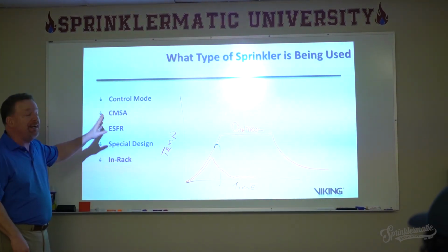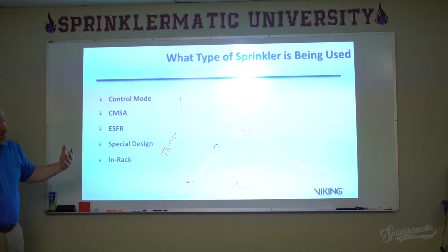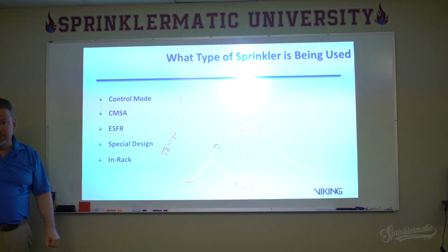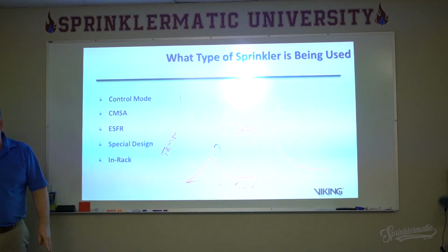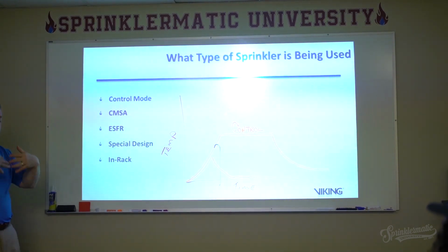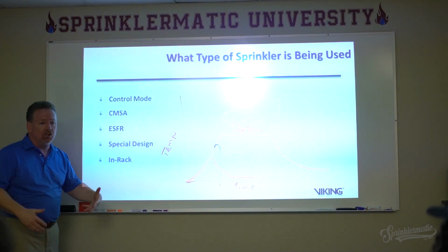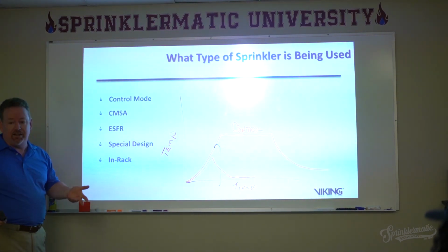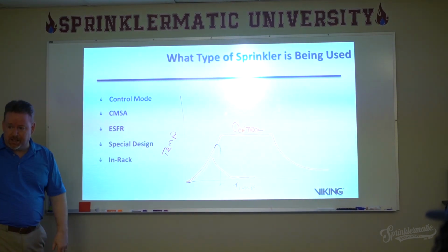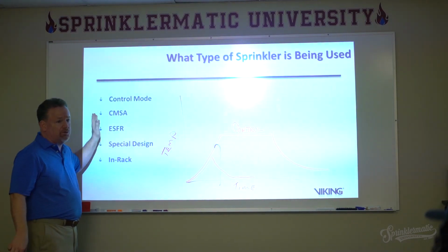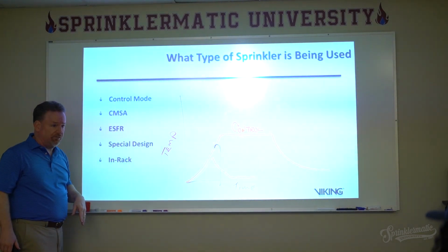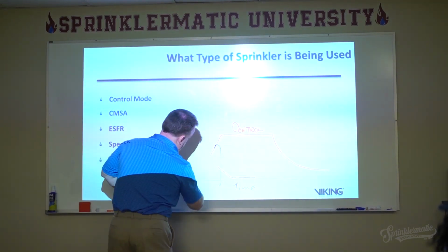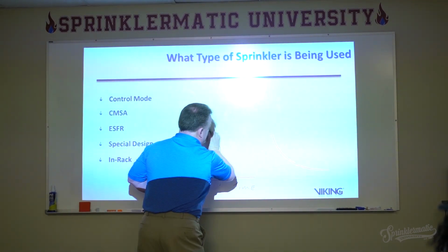Now, they can be used otherwise, but I don't want 100 gallons a minute coming out of a sprinkler in this room. I certainly wouldn't need it. It's over-designed. It's intended to protect against high challenge fires that normally occur in storage occupancies. That's what we've tested these for. That's what they're geared for.